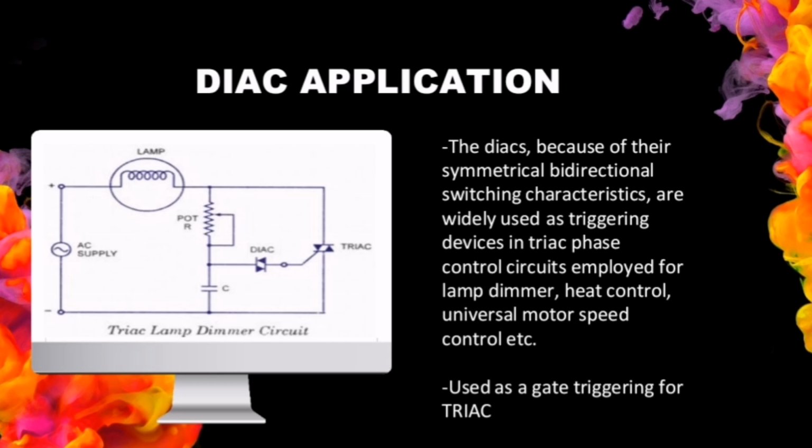In view of their usefulness, diacs may often be built into the gate terminal of a triac. Diacs are a widely used electronic component. The chief application of the diac is for use in conjunction with triacs to equalize their switching characteristic. By equalizing the switching characteristic of these triacs, the level of harmonics generated when switching AC signals can be reduced.